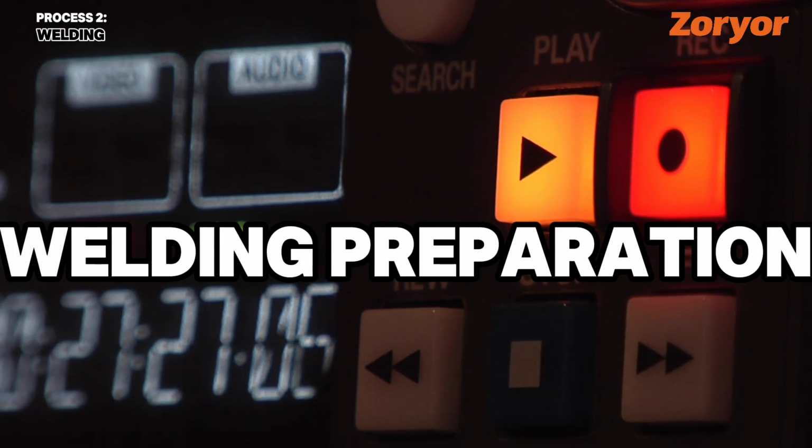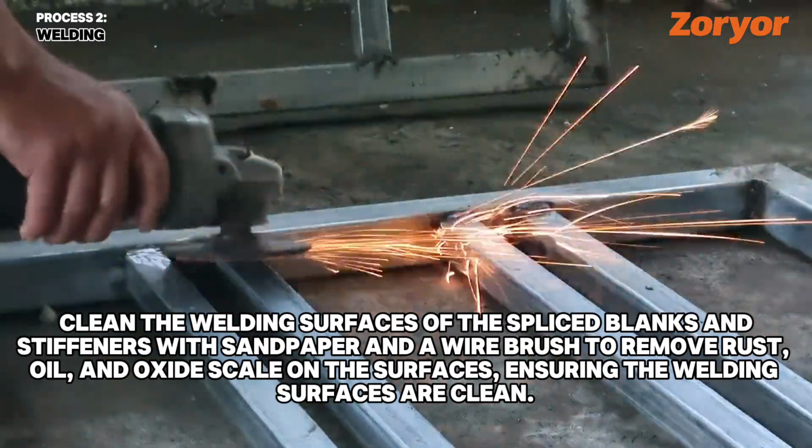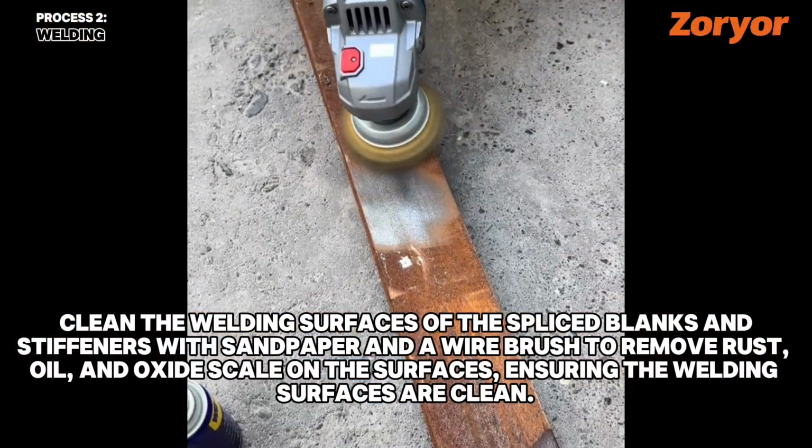Welding preparation. Workpiece pre-treatment. Clean the welding surfaces of the spliced blanks and stiffeners with sandpaper and a wire brush to remove rust, oil, and oxide scale on the surfaces, ensuring the welding surfaces are clean.